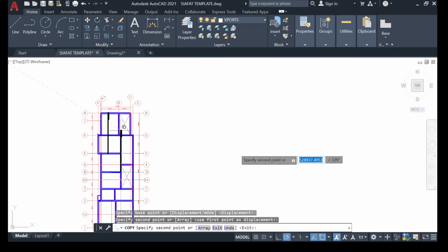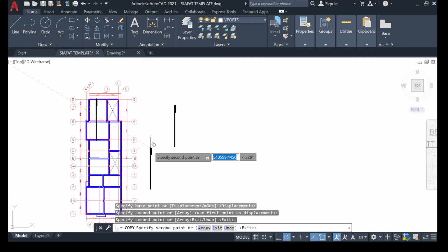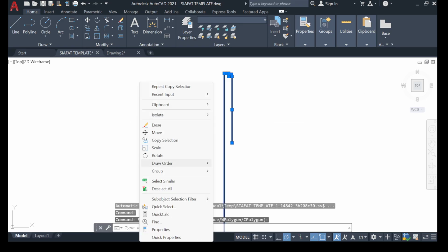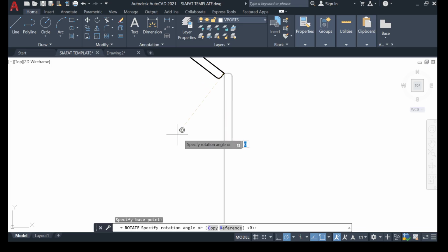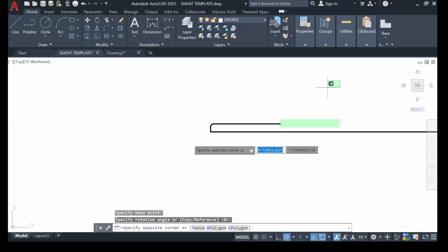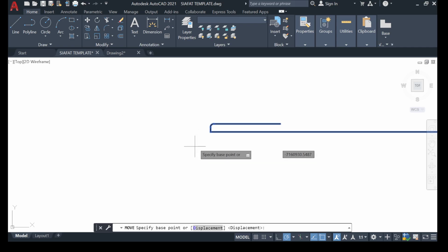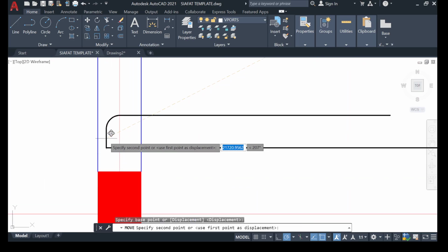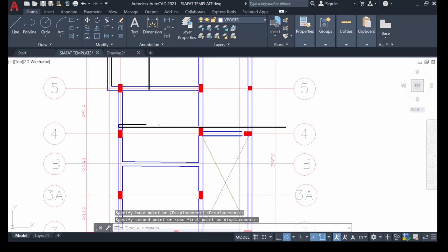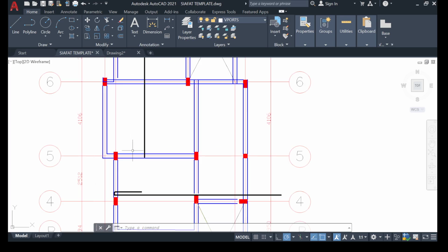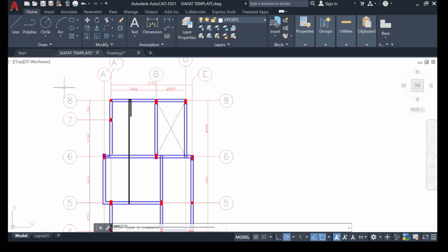Now let's also have our reinforcement for the horizontal side. So let's rotate this and bring it here. Or you could just go and pick it from the template and drop it here. Are we together? So now we have our reinforcement for the vertical side and our reinforcement for the horizontal side.